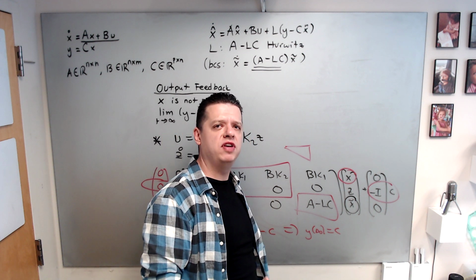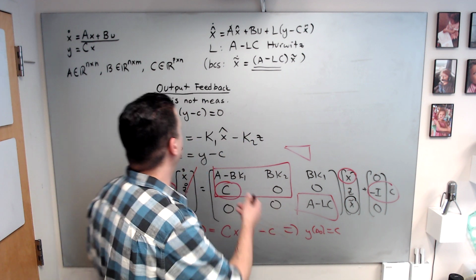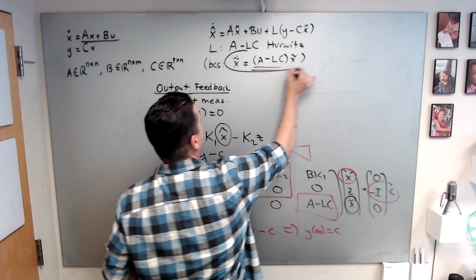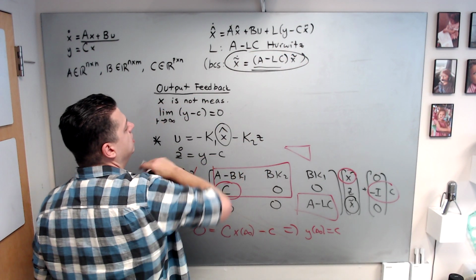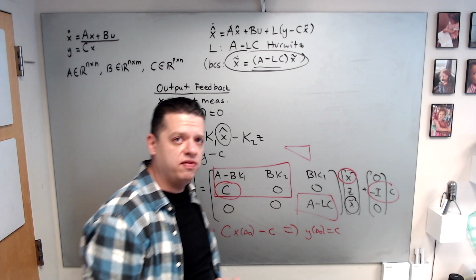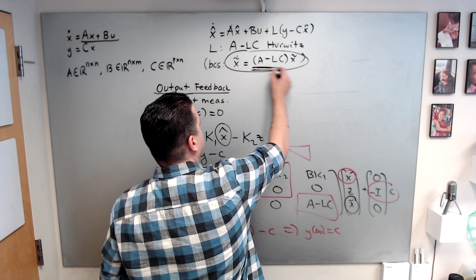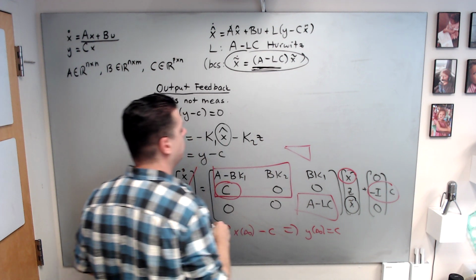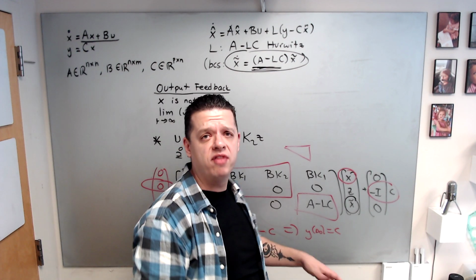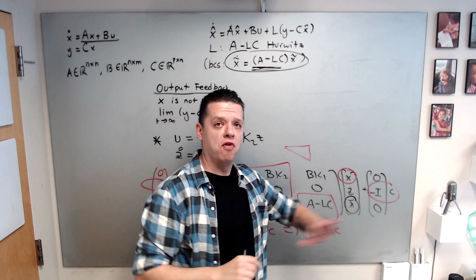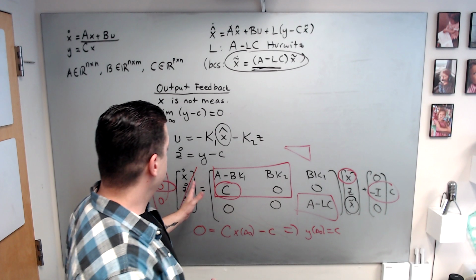It will give state feedback performance even though you are using this. So if this vanishes fast, then you kind of recover state feedback performance. So choose the eigenvalues of this matrix by tweaking the Q and R matrices, or if you are using pole placement, directly place them further to the left for the integral approach.